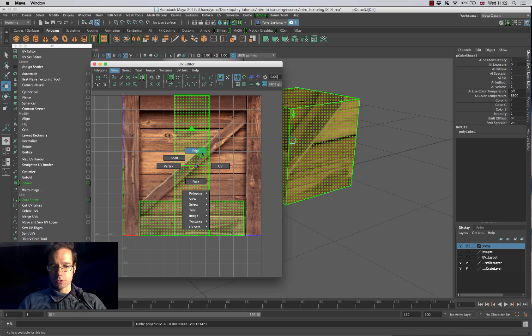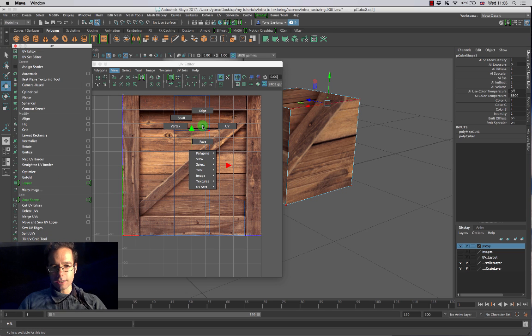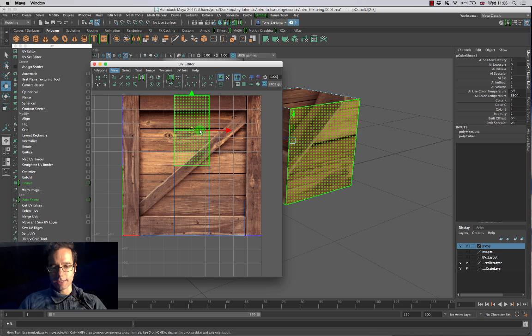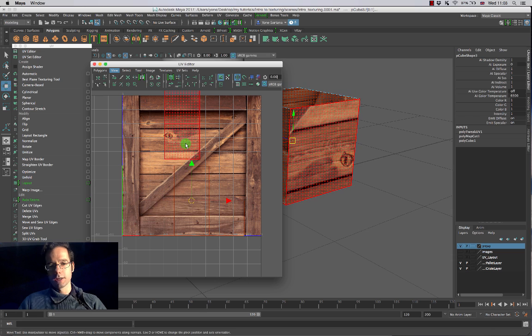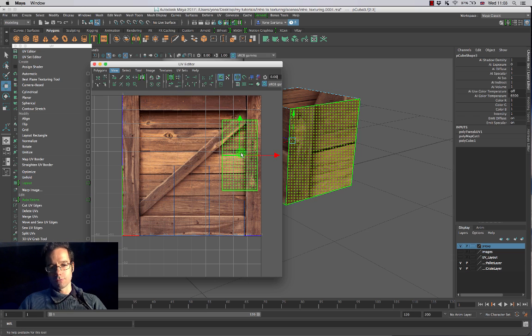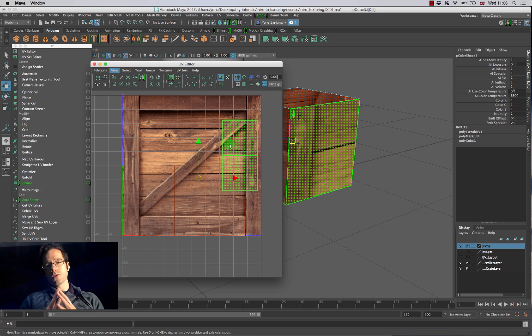And if I went into, say for example, edge mode over here, selected an edge, and looked for my split edges tool, which I'm going to look at as split UVs over here. If I now turn to shell, for example, I can select a new shell over here, because I've just used a tool to cut my UV shell into 2 different parts. So now I have 1 and 2 shells inside of my scene. So the UVs and the shells are two new components that are specific to when we're working with texturing.